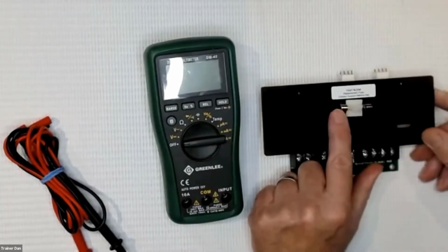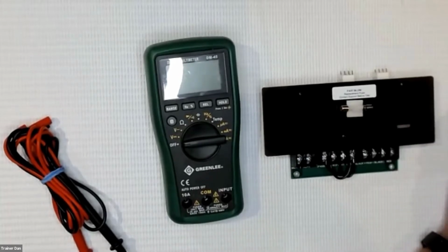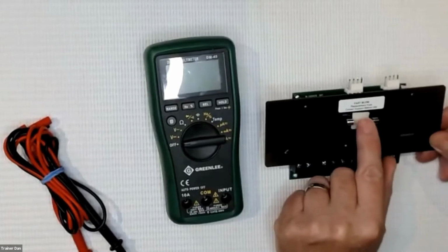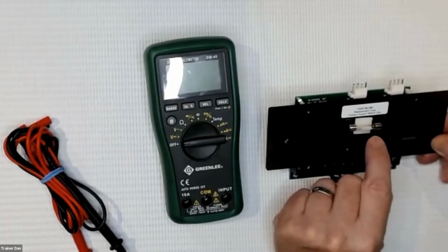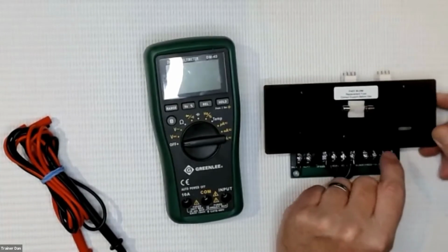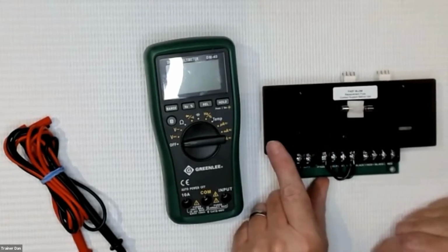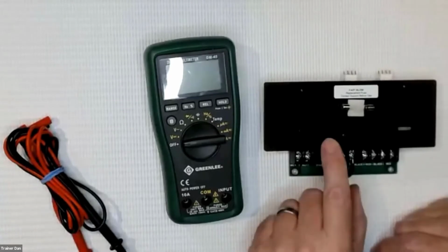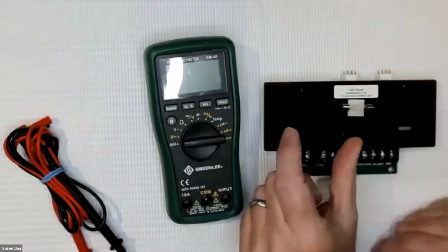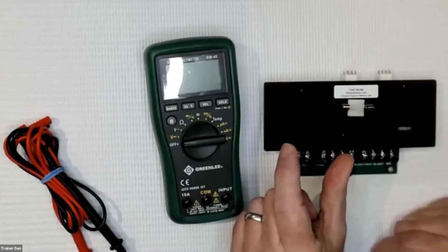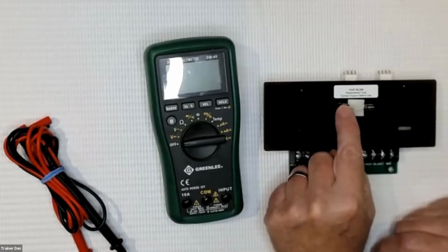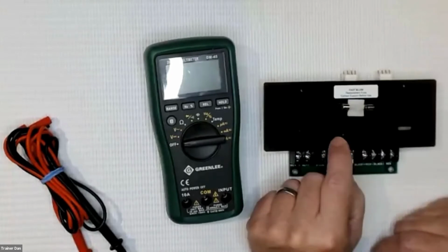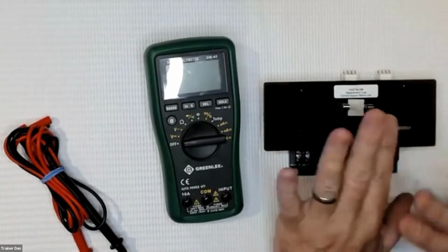Those fuses are hiding underneath here, and I can use the resistance function of the meter to test a fuse. Now, since we're mentioning fuses, this fuse says replacement fuse, contact support before use. It's not uncommon that we open up a controller and not only find a couple of burned out fuses, but find a box of automotive fuses. Someone burned the original fuse hiding under here, burned this fuse, and then had to go buy extra fuses, which is like, time out.